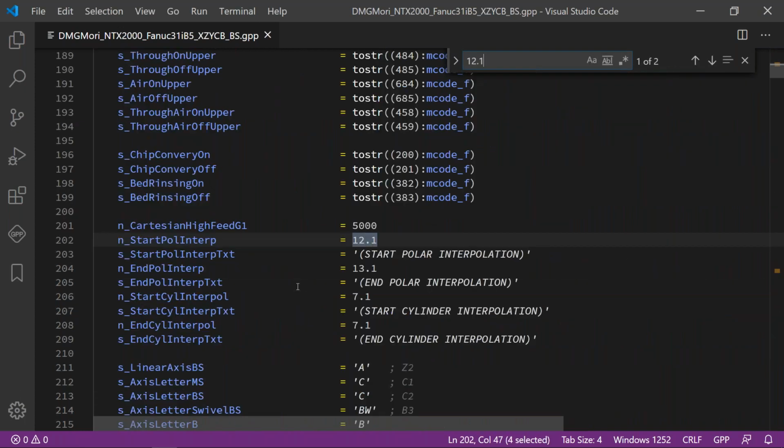I know it will be a little bit difficult for you because this is a post that you've seen for the first time in your life. But I will show you how it is in most posts, and you will find similarity, I'm sure of that. You will see what I will do and what steps you need in order to modify this. So there's a variable here called 12.1, and this variable has this value in order to print it correctly. Here we have a Cartesian feed that we will not need anymore, and these are just the comments, and this is to turn it off.